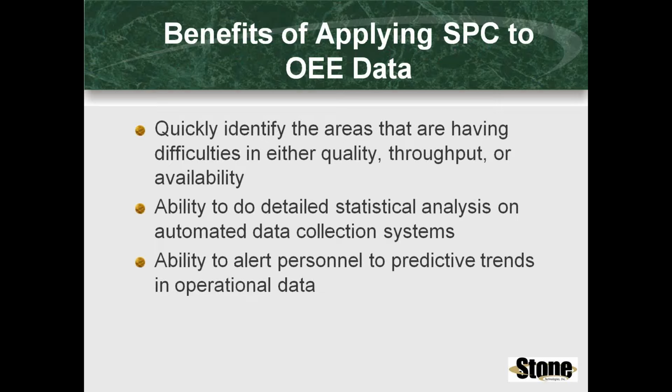So why do we apply SPC to OEE? It helps us to quickly identify the areas that are having difficulties in either quality, throughput, or availability. It gives you the ability to do detailed statistical analysis on an automated data collection system, and also provides the ability to alert personnel to predictive trends and operational data.